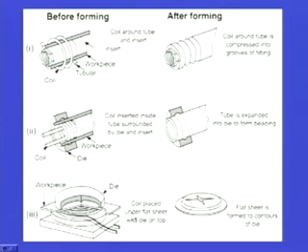So, the coil has been placed under the flat sheet, that is the workpiece, with a die on the top. Now, the flat sheet is formed to the contours of the die. So, whatever the contours inside the die are, the flat sheet will be formed according to those contours and take the shape of the die.